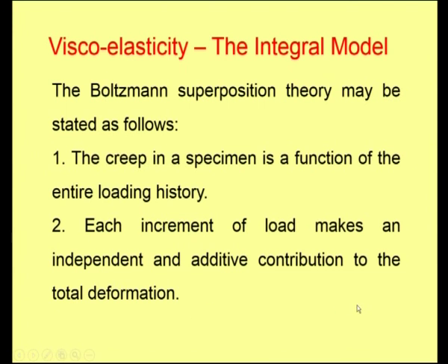The creep behavior is simply a function of the entire loading history, in the sense that if the material was subjected to load previously, some creep will be there, and that creep has to be added. For example, if you load it with 5 newtons, 10 newtons and 15 newtons, it is similar to loading with 30 newtons. That is the second law, that it is additive.